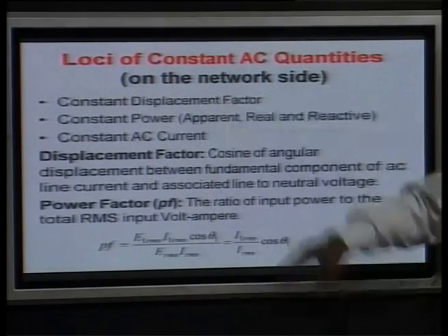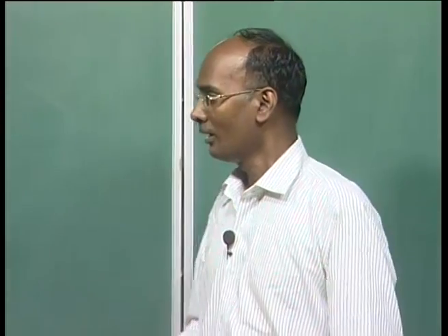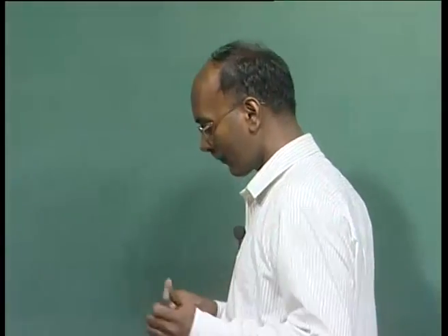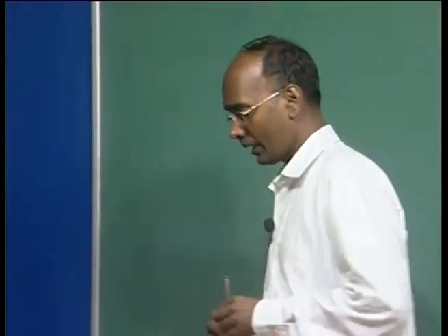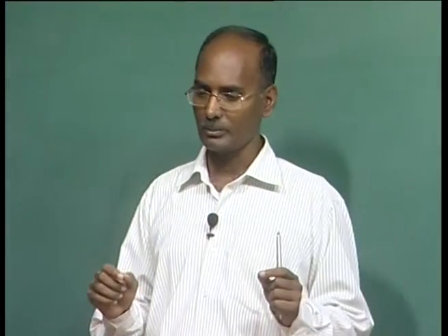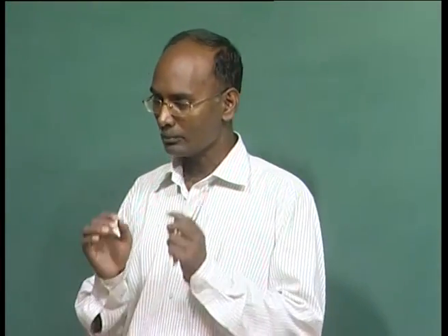Here I am going to draw the displacement factor, not your simple power factor. To know the difference between the power factor and the displacement factor, as its name suggests, first we have to define what the displacement angle is. Displacement angle is the angle between the voltage phasor and the fundamental component of current.